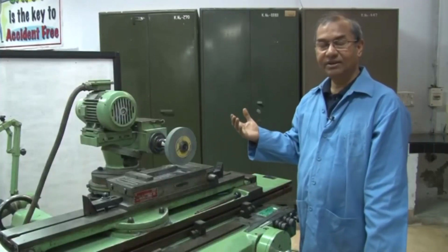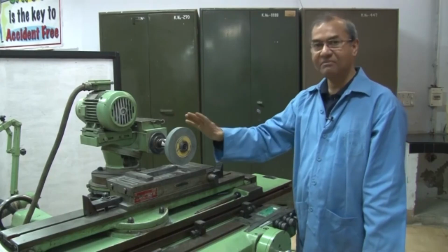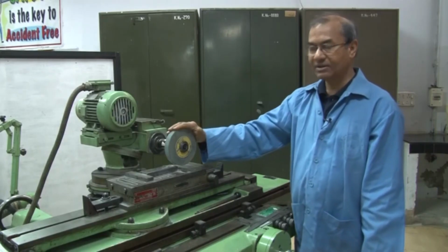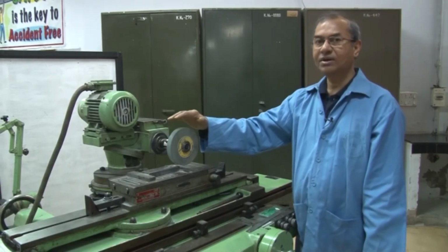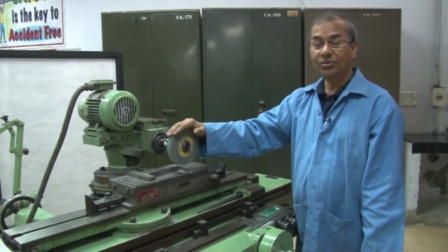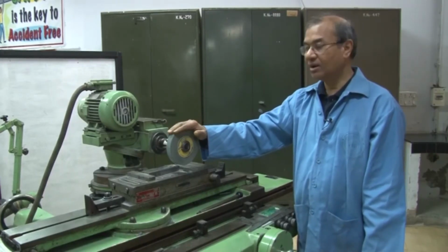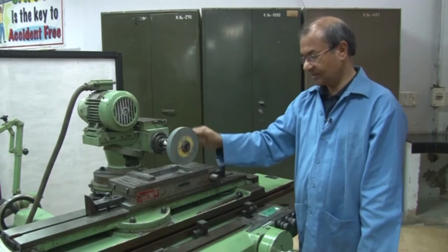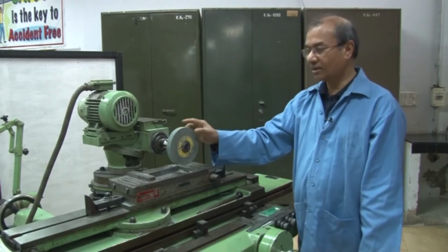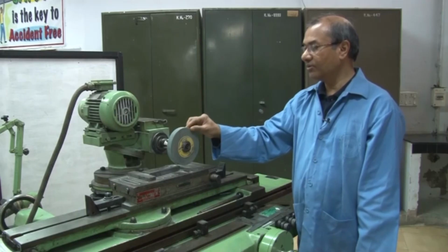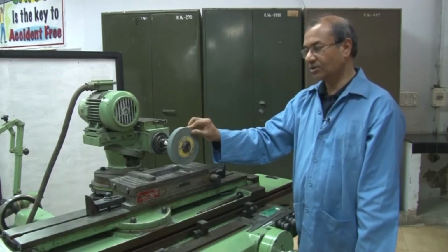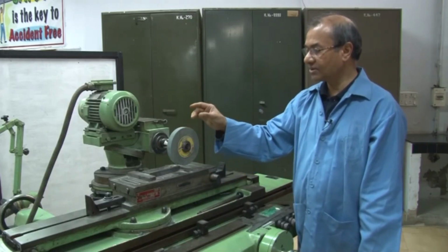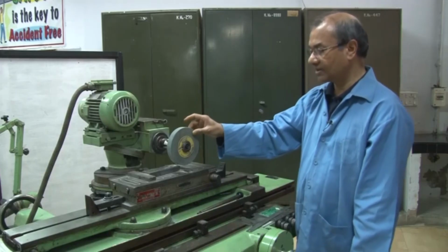Well, to continue with the grinding process, now in the same machine you can see that the grinding wheel has been changed. Earlier, it was a cup type grinding wheel which was used for grinding the side rake of the tool, and then the face of the drill, but here we have changed the wheel to a wheel which is capable of doing surface grinding. Surface grinding, as you know, makes a flat surface. So, here is the wheel which is used for the surface grinding.